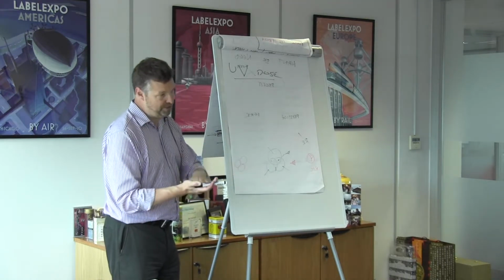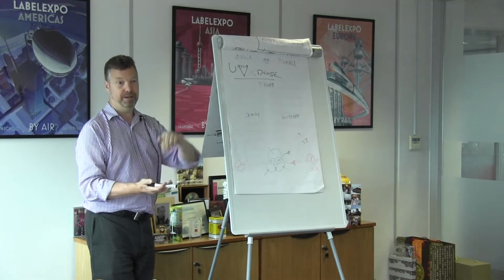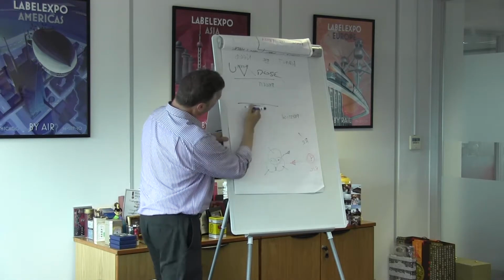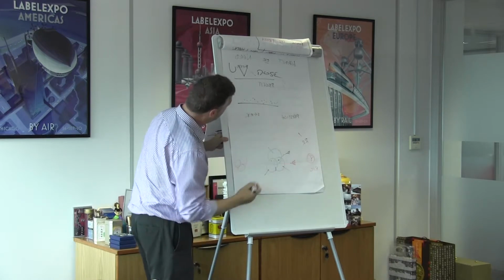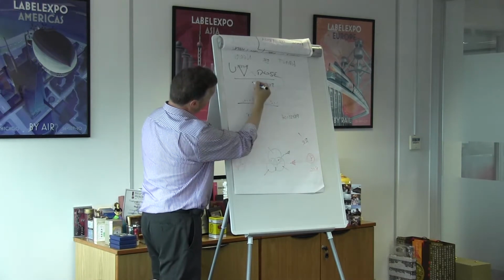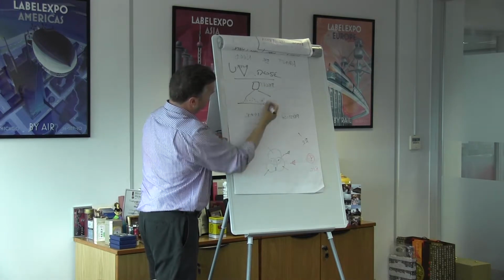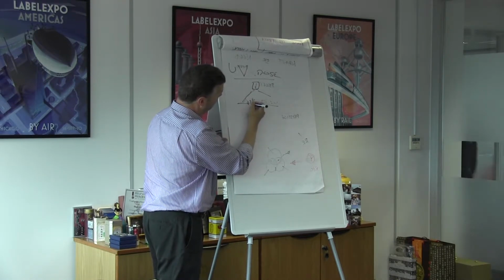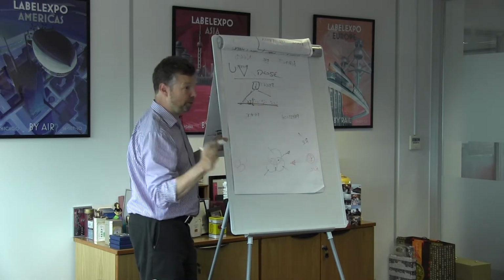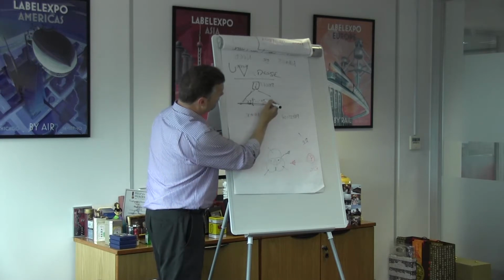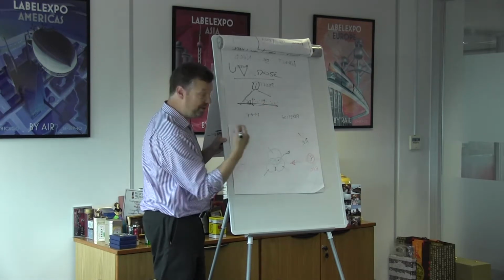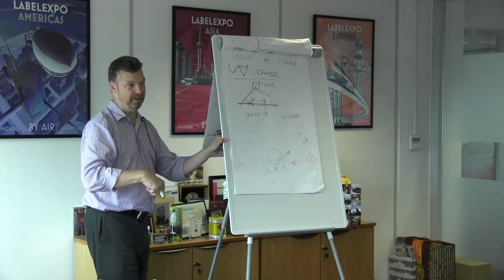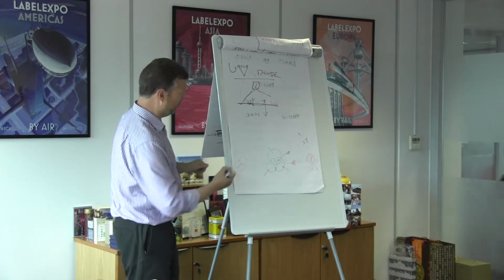But the key thing about UV is that you must have enough UV energy or power onto the web to get those buzzy bees, okay? Because there's the ink, it's the buzzy bees, which are the photo initiators. And they're buzzing around with loads of energy. Then you've got your UV lamp up here. And if I get a certain amount of UV power coming down, all those will be bonded to the web, and that will become like a solid film. But as I said, the problem is, if you don't have enough power, then some of those are so powerful, with so much energy, they can go right through material, right through a bottle. So they're really kind of nasty stuff. Once they're in the bottle, then they're in the food, in the drink. And that's where the problems start to come, because they're carcinogenic.